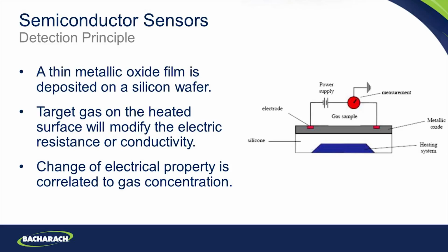The way this technology works is such that actually any reducing gas will cause a reaction within these sensors. In normal operation, oxygen molecules will be pulled out of the atmosphere onto the metal oxide film, and when a reducing gas hits those and causes an oxidizing reaction, then the conductivity and the resistance of the sensor changes, which we measure.